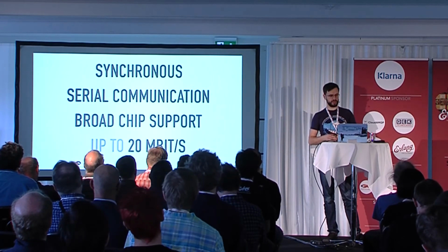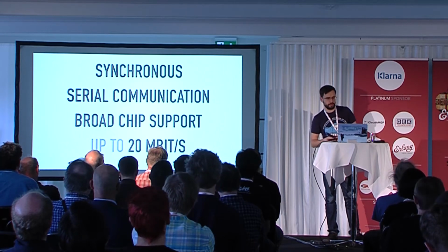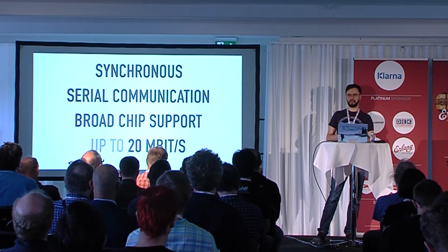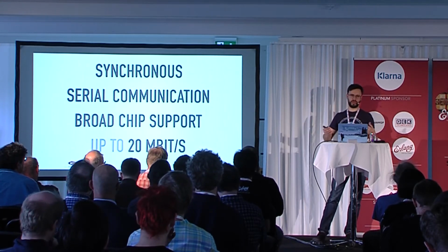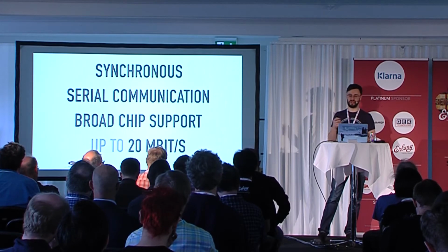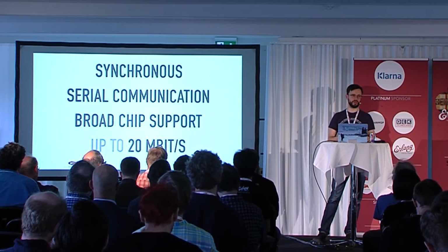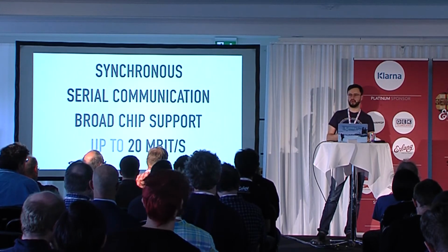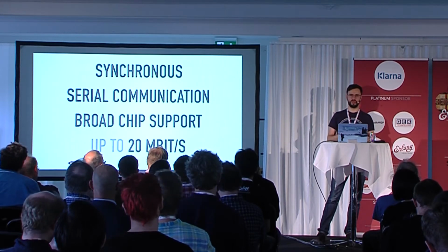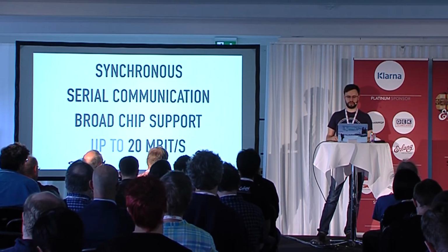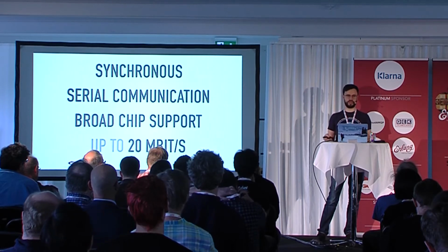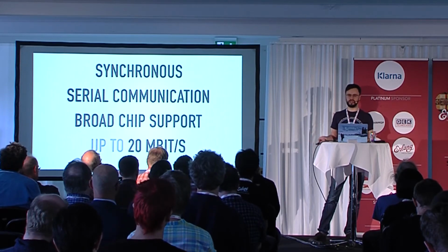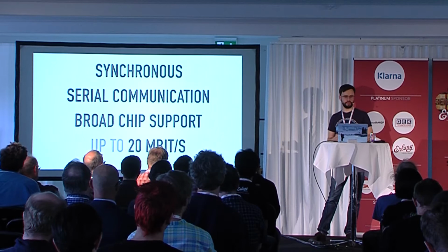SPI is a serial peripheral interface, and it's synchronous serial communication. It's a bus, and it is kind of simple like GPIO, but you have this serial aspect of it, and it has very broad support among chip makers. Lots of chips just know how to talk SPI. It's a pretty standard protocol. For example, you can have oscilloscopes that can show you the SPI, so you can debug the SPI on the wire, lots of stuff like this. There are many nice components that know how to talk SPI, and we do as well.